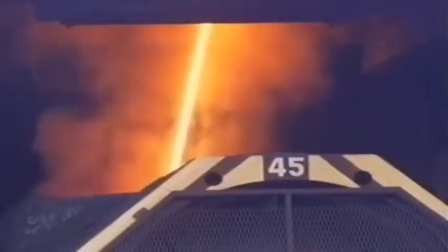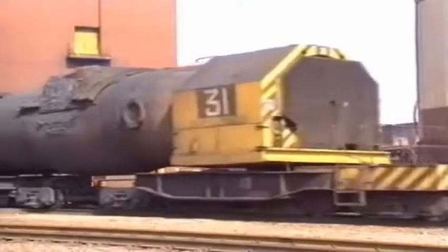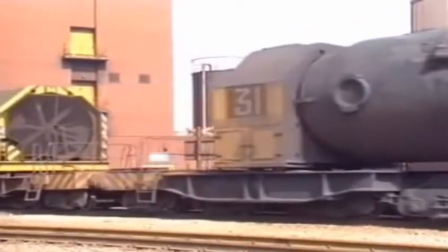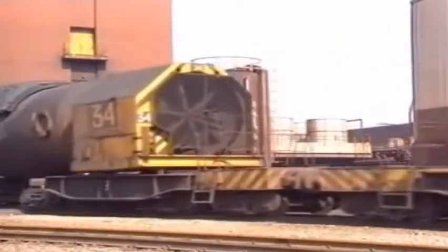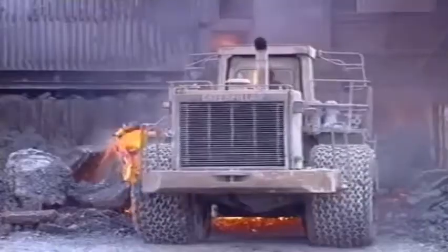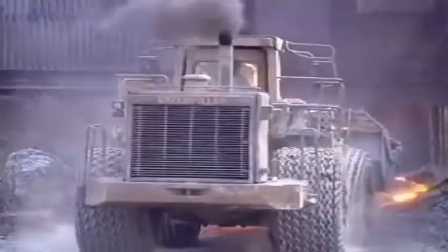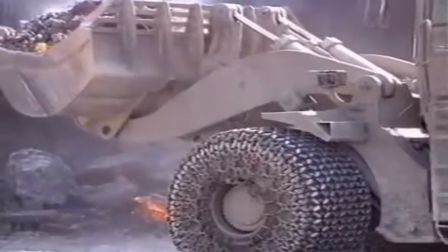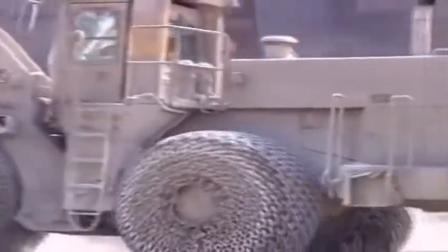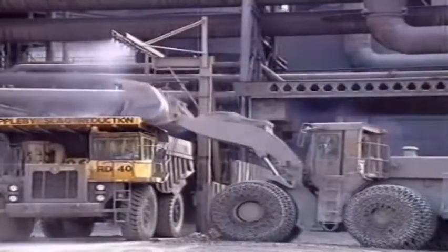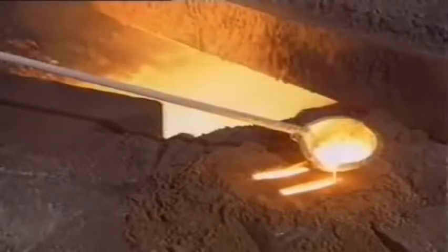Between 10 and 20 times a day, the molten iron, called hot metal, is tapped into torpedo ladles. Torpedo ladles hold 300 tons of molten iron. Molten slag floats on top of the iron and is tapped along with it. The slag cools and solidifies. It can be used in cement and for road building. At this stage, the molten iron contains around 4% carbon and other impurities. The iron is brittle.